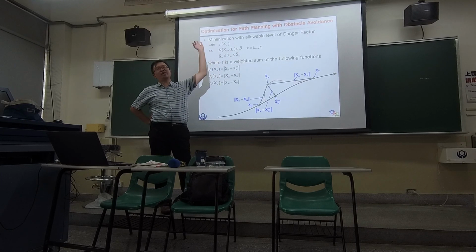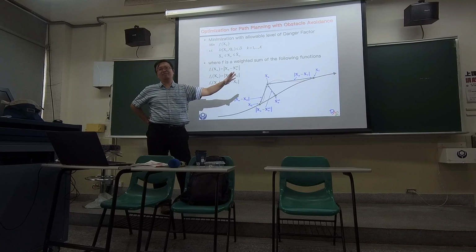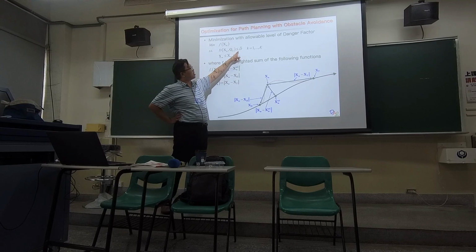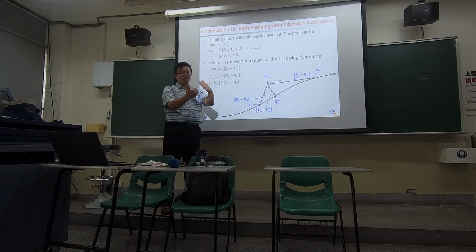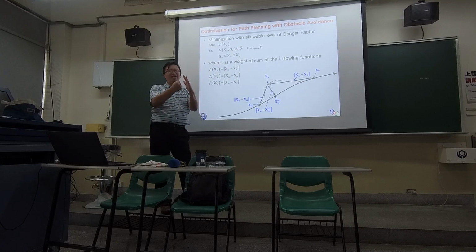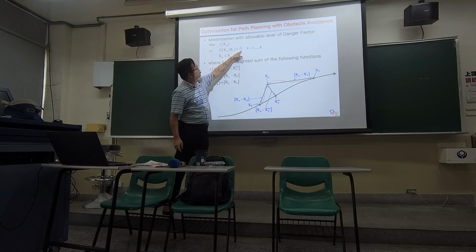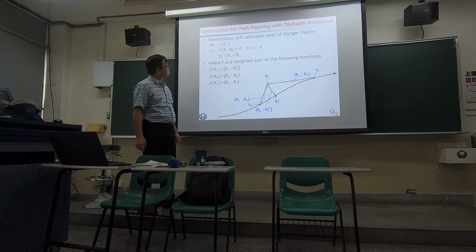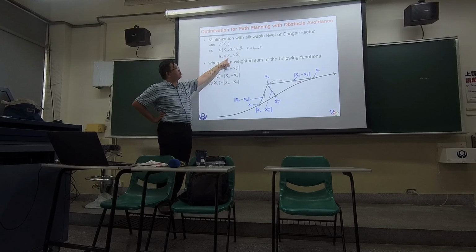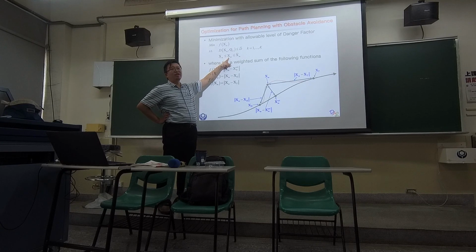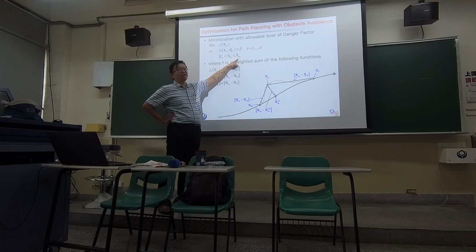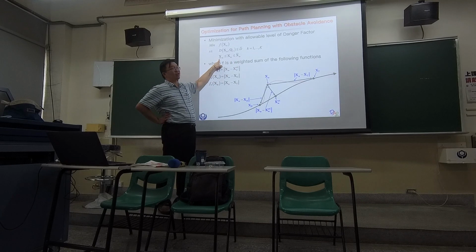If it's greater than 0.5, collision happens. You can set it as 0.4, so you will be keeping a safe distance away from the cylinder, because 0.5 is like a point contact. 0.4 is a little bit far away. So usually we use 0.4. And your joint angle is limited by its largest angle and the smallest angle.